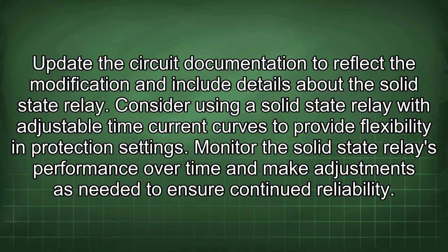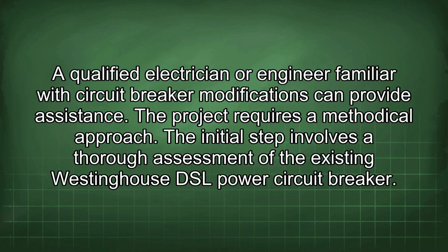Consider using a solid-state relay with adjustable time current curves to provide flexibility in protection settings. Monitor the solid-state relay's performance over time and make adjustments as needed to ensure continued reliability. A qualified electrician or engineer familiar with circuit breaker modifications can provide assistance. The project requires a methodical approach.